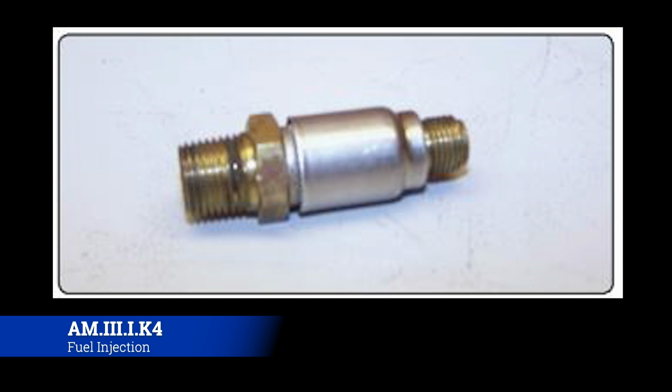And basically, if you don't have all of them in good working condition, that engine is deadlined. And so whenever you go to take these things off, be really careful not to damage them, and also be very careful not to lose them. But ultimately, all they are is a little bitty brass nozzle that has ports in it to allow the fuel to get pressurized inside of it, squeezed, and then pushed out those little ports, so that way it can mix properly with the air to cause combustion.